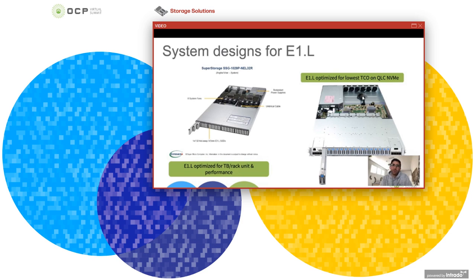That's really bad for thermals. So E1.L solves this problem by spreading out the components on a long PCB, and then they're all thermally bonded to the aluminum enclosure. And then you can see they have these latches and LEDs in the front, so it's easily hot plug, serviceable and removable from the front of a server.